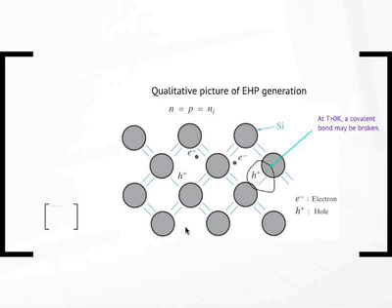So remember, this is silicon. So silicon shares one electron with its neighbor, 4 neighbors. So 4 electrons shared with 4 neighbors. Each bond has 2 electrons. Remember? That's the picture of silicon, which we saw last class. Okay? So now it has a hole. The electron's free to move, say it's somewhere here, and it has a hole. So that's an electron-hole pair.